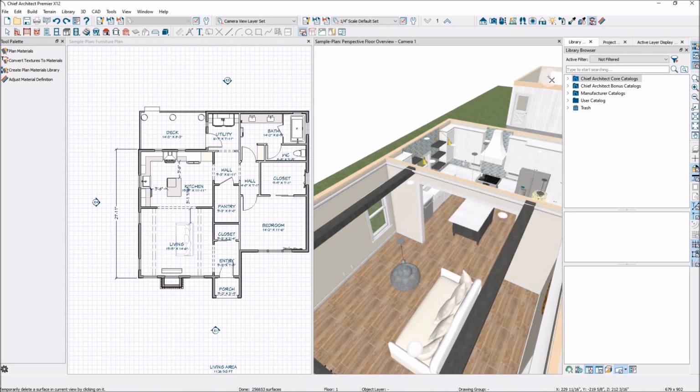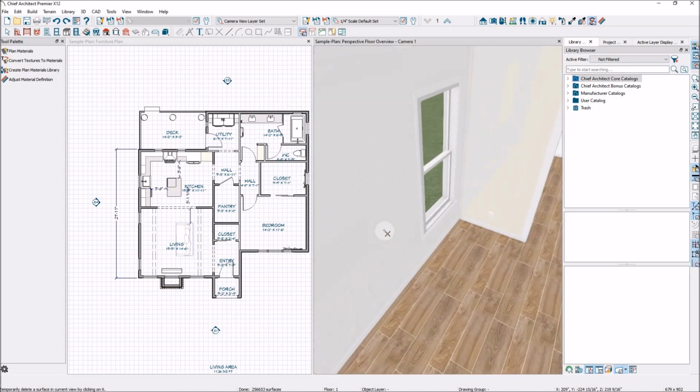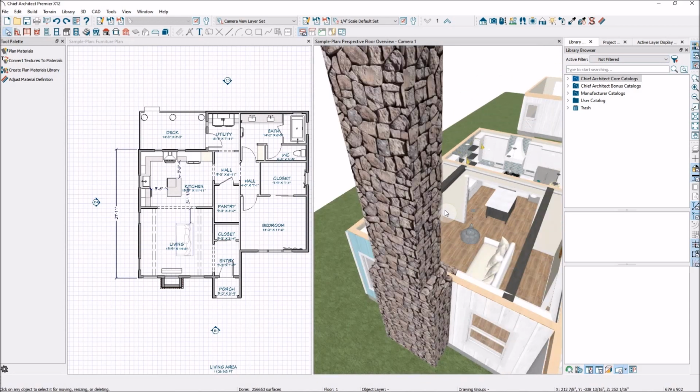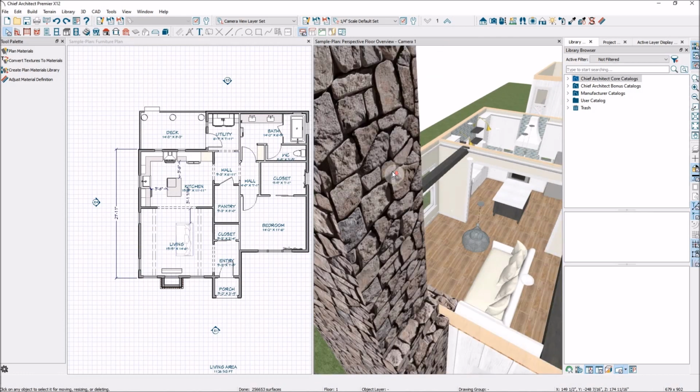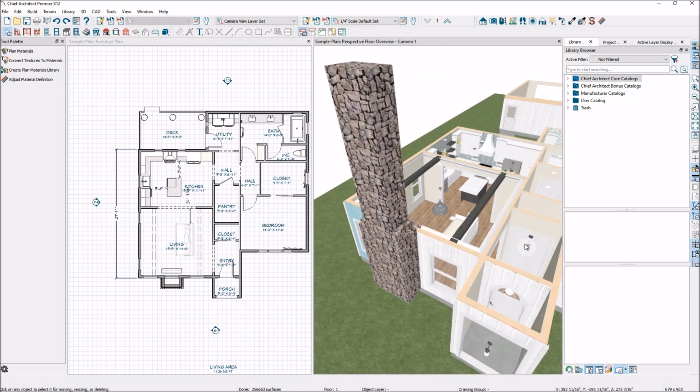Okay, so another way that the painter is very handy is to add paint texture to your wall. So I could go in and add a texture to this wall and then paint over that. The thing that you need to remember if you are doing renderings is that when you use this paint tool, sometimes it does not change the default within the object itself.